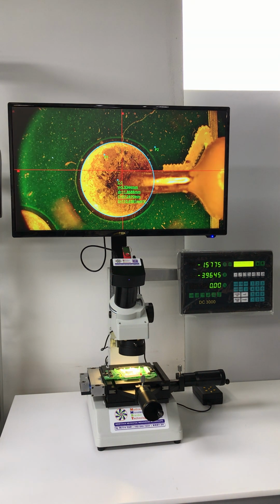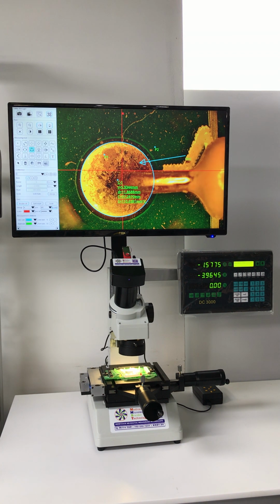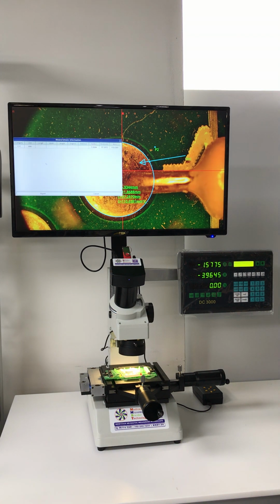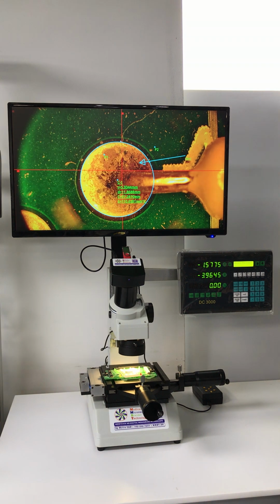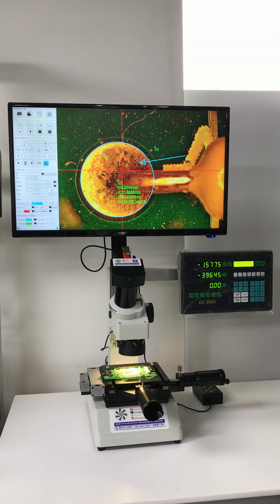You can do annotations by simply clicking on a point, adding some text. That way if you want to make notations of any defaults or any defects. And if you ever want to save it, just export. So this will do all your measurements, the units, and then the perimeter, radius, and area. And then to delete all, simply click delete all. And then to go back to the camera settings, you can click measurement again. And this way you can bring in and fine tune it.